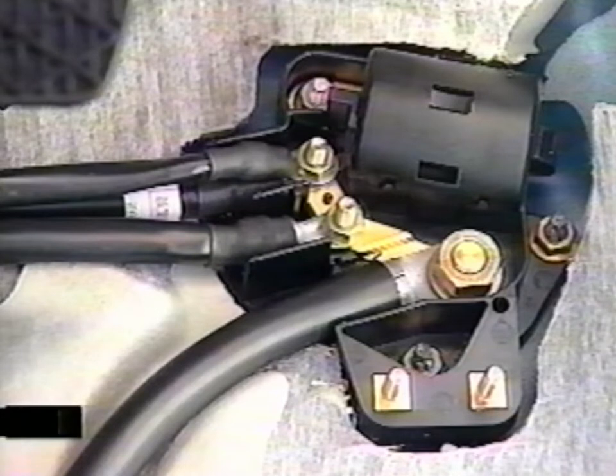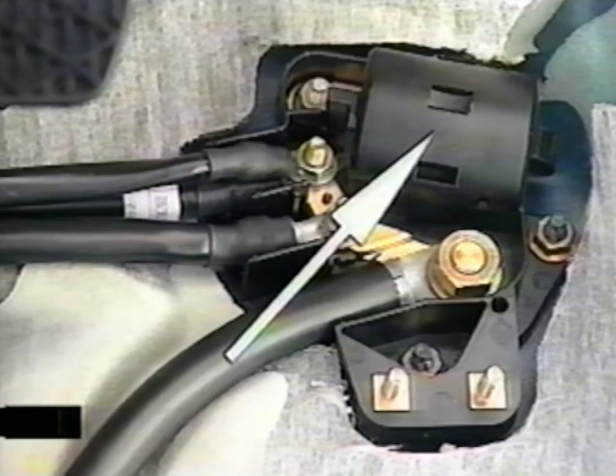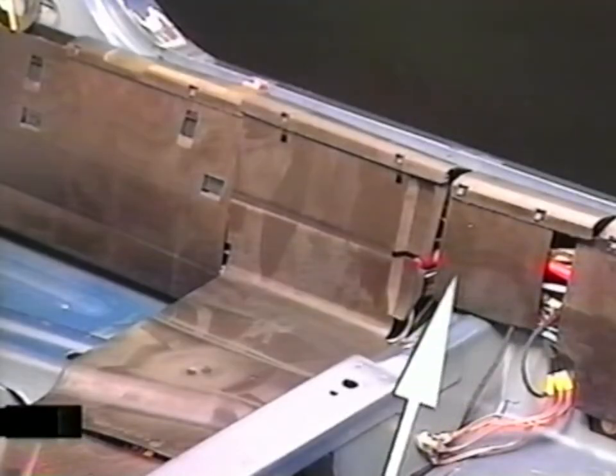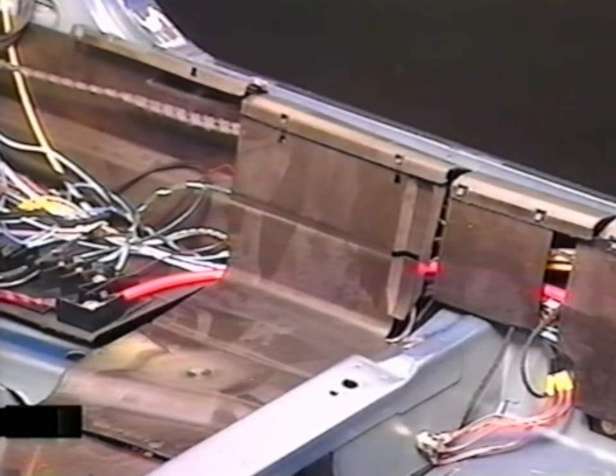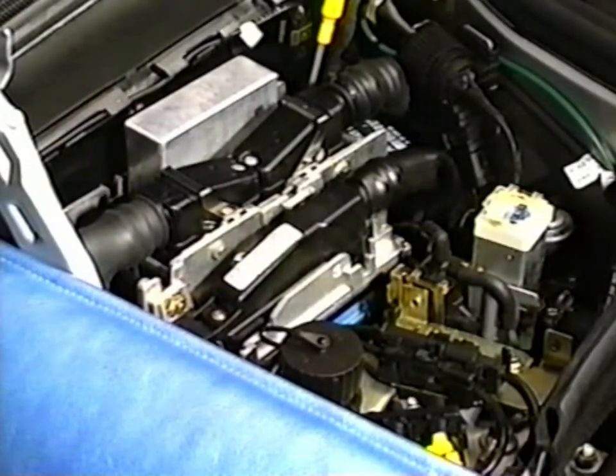The large cable terminates at connector X4, and the alternator and starter cables connect at this point. A capacitor is included at X4 to suppress electrical interference from the battery cable. And finally, the third cable, the small red battery cable, is routed in the right wiring duct and supplies only the control modules found in the right side of the component compartment.